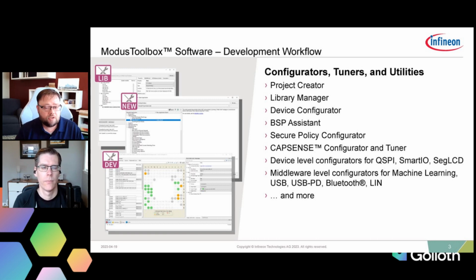A library manager, which we'll see in part of the demonstration, of being able to reach out and say, okay, I've got my project up and running, but now I need to extend it by bringing in the Golioth SDK inside of it, or I need to bring in this other library or piece that I want to supplement my application. The device configurator, which is where we're going to do our initialization setup, handling all the clock configurations, handling all of the pin muxing, and how we're going to use different peripherals. And the list goes on.